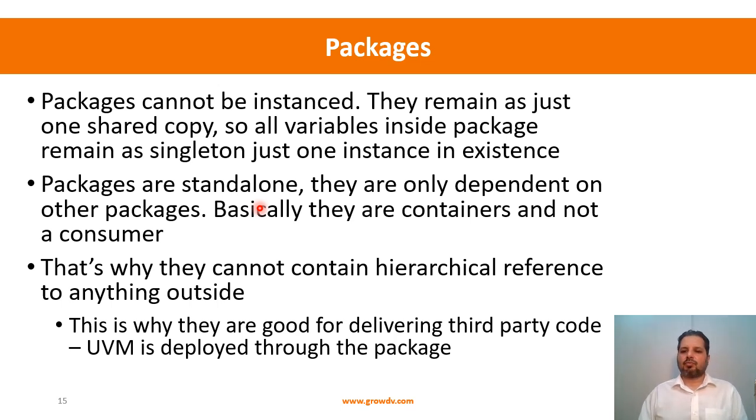In a package you can't put an initial block and call whatever tasks or functions you have declared. They don't have that type of existence where the code can execute within the context of the package independent of another container. So they are just pure containers in that way. Since they do not consume anything, they just remain standalone. And if I had a class, or if I had instanced one more module and that module contained a class, then when I call them, I have to use, like, top tb dot, some internal module, and then I call that particular task.